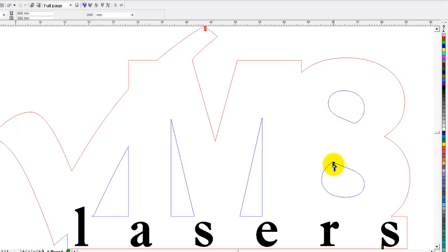That's critical in any laser engraving project. And if you have objects in the center that you want to do something different, like I did here, etching, then you want that to be second. And if you do the outside completely cut out, that'd be third. And just click on that.